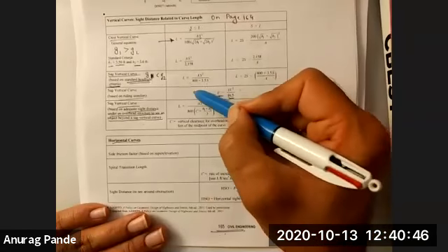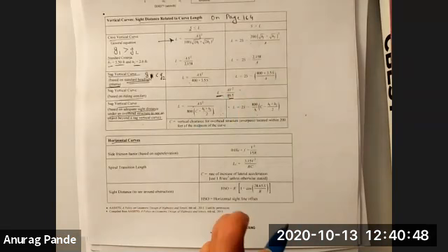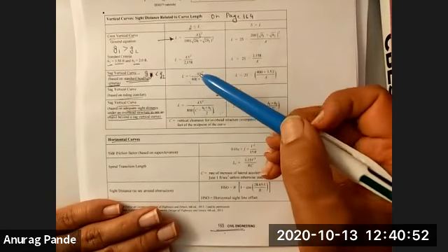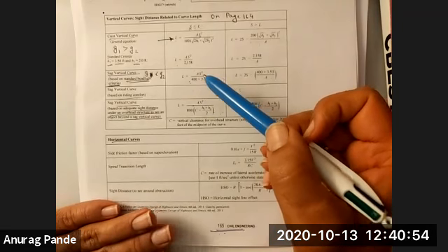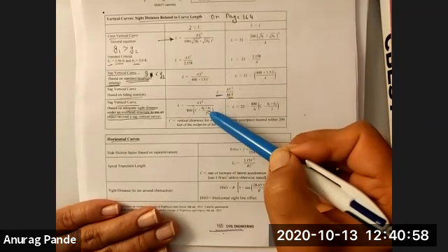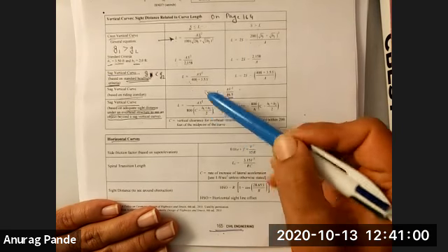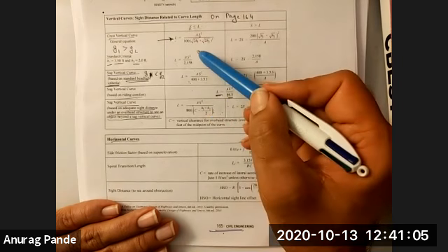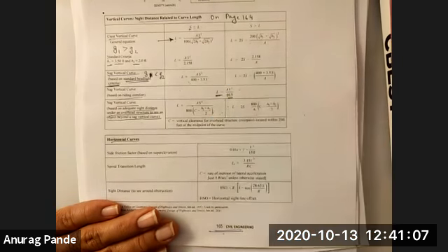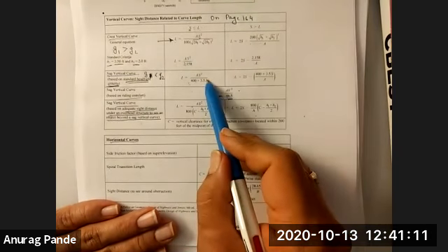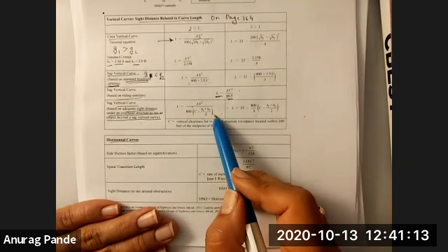All these formulas are essentially giving you the minimum length of the curve required, and you want to make sure that the minimum criteria is met based on all three things. So you provide the highest value that you get from the sag vertical curve calculations using these three criteria. For a crest vertical curve, there is only one criterion, sight distance, being able to see beyond the hill. So that's not a problem. But for sag vertical curves, all three criteria apply.